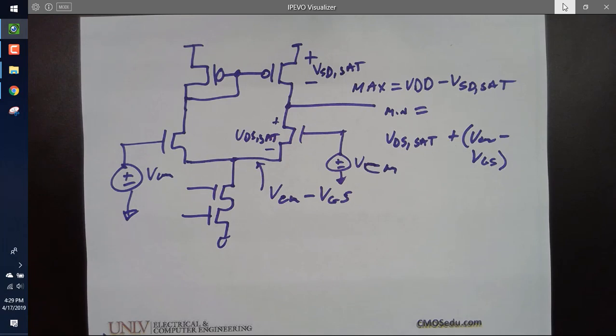So now I want to be able to simulate it. So let me ask this. Does it matter for the max what VCM is? No. But how do I simulate things? Oh, by the way, what is the gain of this diff amp that you calculated? 333? So if I put in 10 millivolts on one of them, won't the output swing by like 3.33 volts?